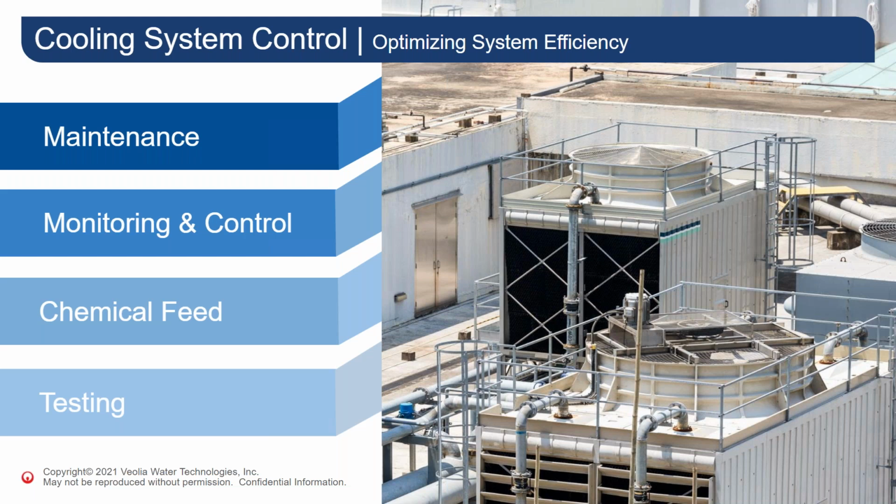The operation of this chemical treatment program is equally important, so the equipment that supports this program must be maintained as well. This includes periodic calibration of pH sensors, rebuilding chemical pump heads, and replacing chemical tubing. Lastly, regular testing of the treated water to ensure the program is operating as designed is very important. A wonderfully engineered cooling system and its chemical treatment program is useless if the equipment fails due to a lack of regular testing and tweaking.